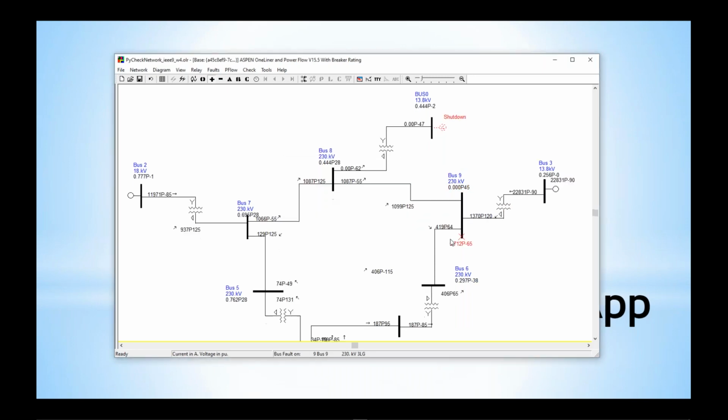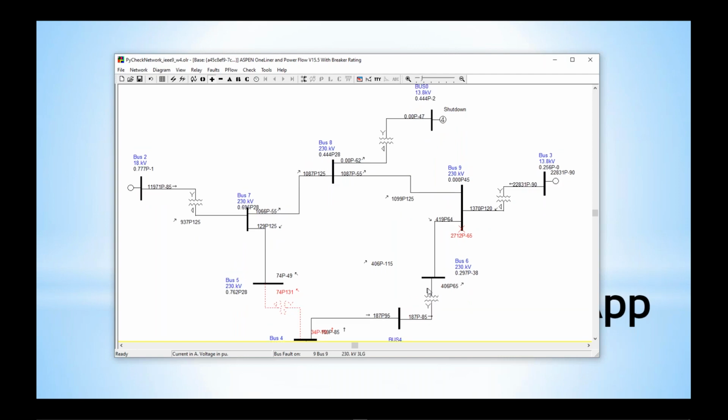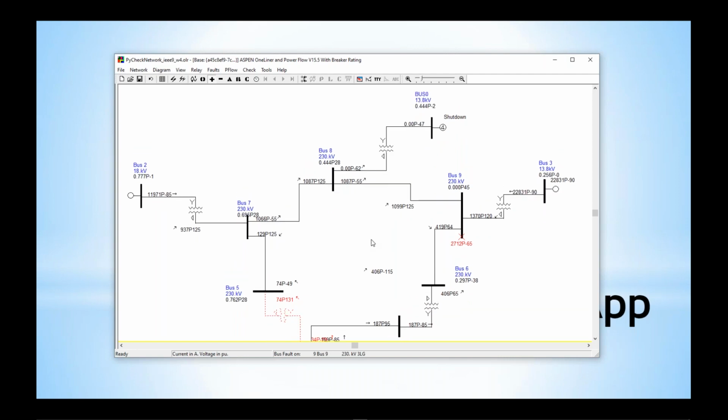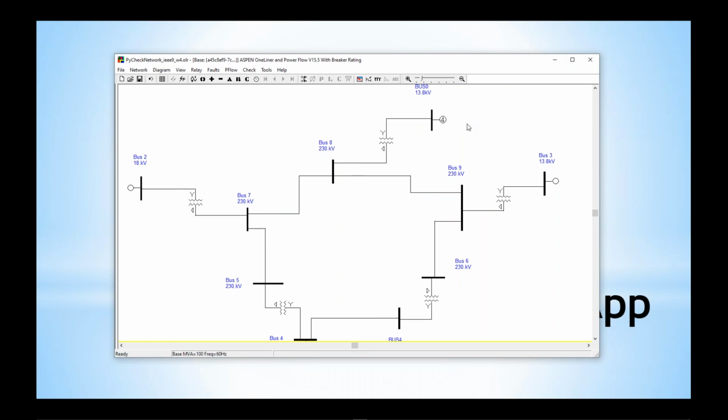The first thing I investigated is that this transformer seemed to be incorrectly set up. As a further check, I want to see if I can make a simplified network of just this portion, so I don't have to care about all those other things, to see if my system is still running, and whether or not this model is correctly built as well.